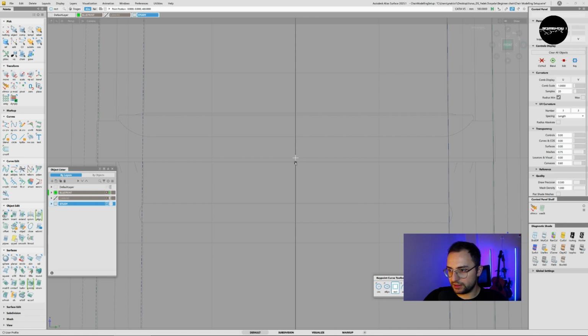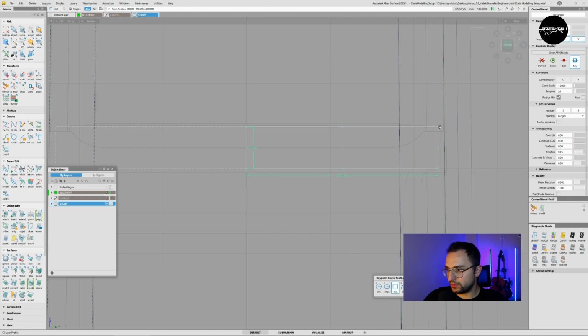Alt and left click. Yeah, and I'm gonna move a little because is it this curve or this curve? I guess this curve. Yeah. Set pivot. Since I'm modeling symmetrically, I should set this pivot in the middle. Left click and control key, and shift control, middle mouse button, scale. I'm just scaling on the Z axis by using right mouse button.